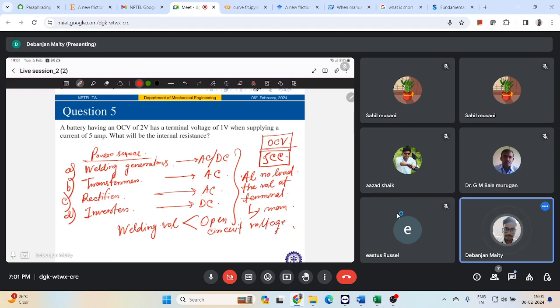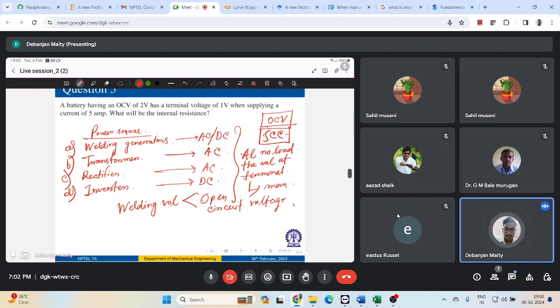Open circuit voltage will always have those high values to provide stability in your arc. In transformer type power sources, the OCV is established by the incoming line voltage and the primary and secondary windings in your transformer, and based on those ratios you will generate some open circuit voltage.